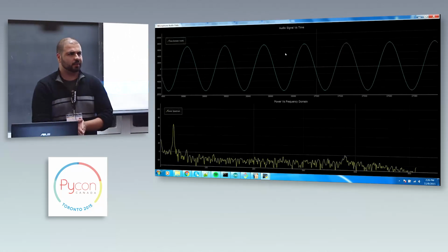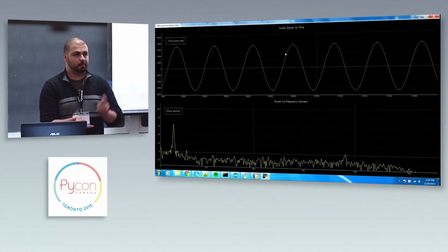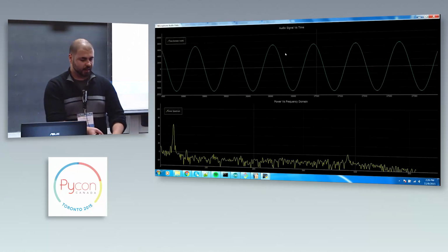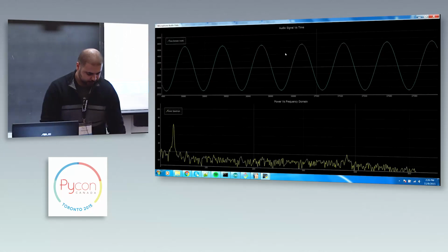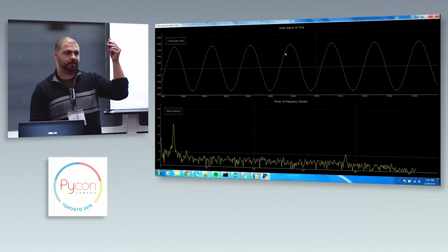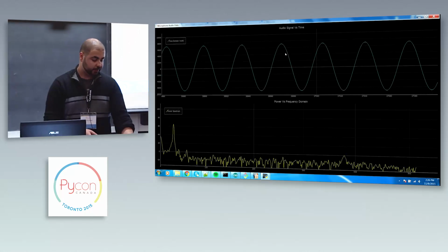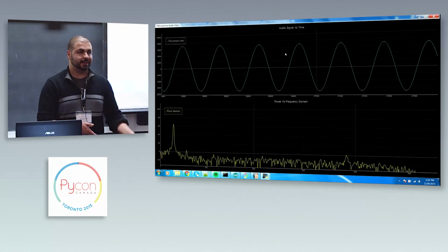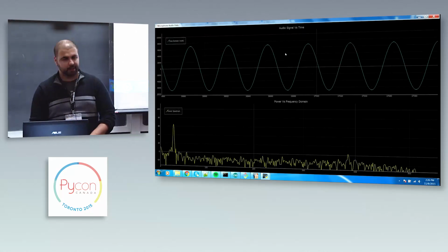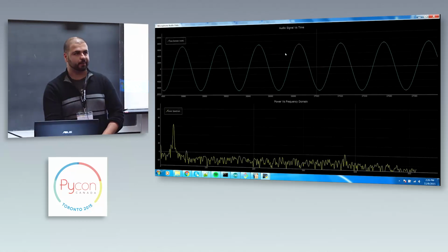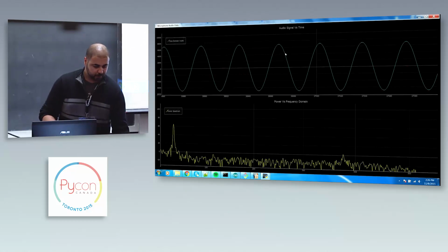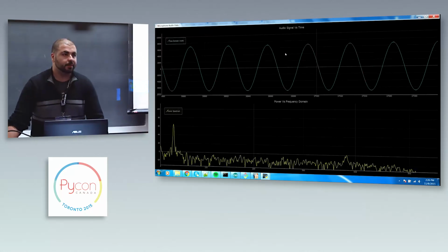So if you go to sparkfun.com, they have a bioamplifier. They have a muscle sensor. They have a heart rate sensor, which is this thing. And I also bought this pulse sensor from there too. So that's one to start. Get an Arduino and start using that, because you do need a microcontroller to at least read the signals. You can't use your microphone. I tried that, but the thing is really bad at very low frequency signals, unless you have a really good sound card. So yeah, just look into the hobbyist websites.